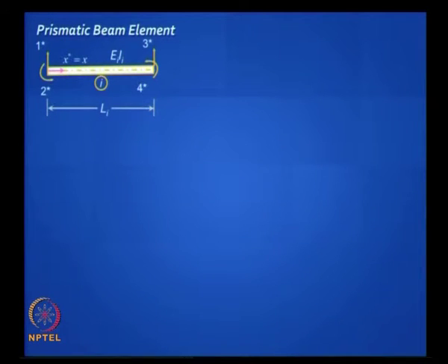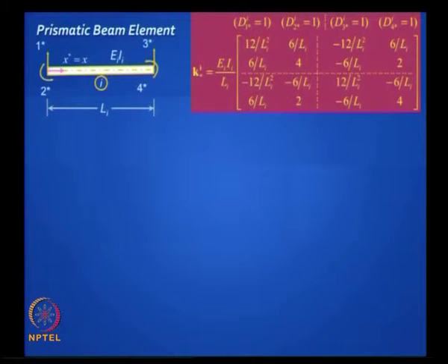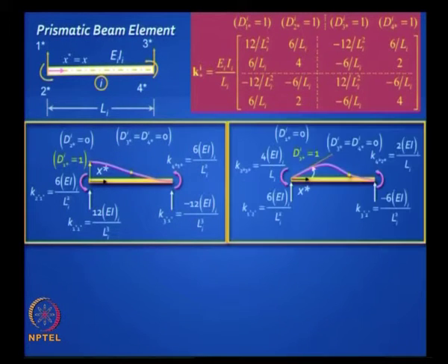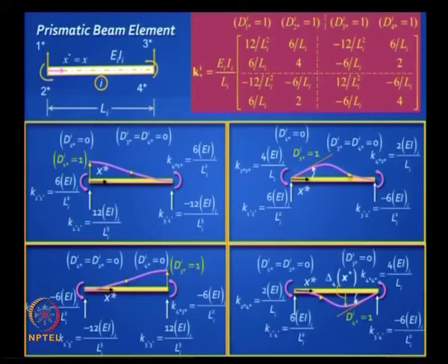For a beam element, without much ado, the stiffness matrix will look like this. We will study it in depth later. You already have a clue why it will look like that. You can break it up into 4 parts. We will study it in detail later, do not worry too much about it. You can fill up this matrix. Here it is a function of EI. Remember 4EI/L, 2EI/L, 6EI/L squared, 12EI/L cubed, that is all that you can get.